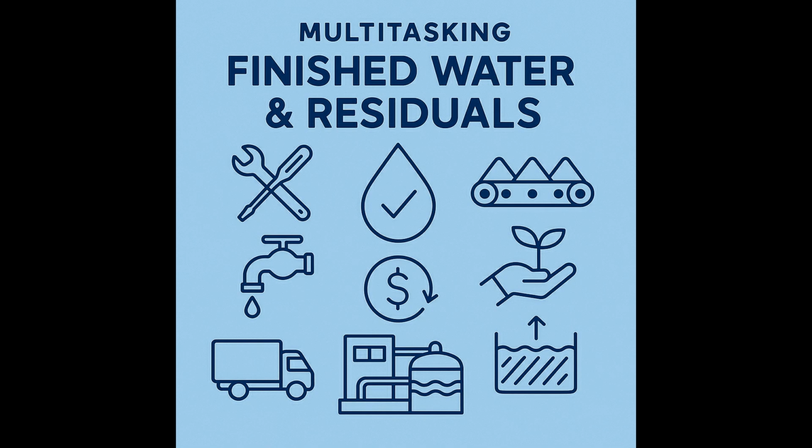Makes sense. You also mentioned operating hours. How does that play into ROI? Well, operating hours and shift schedules tie into staffing and storage. Some plants might choose to process residuals only during, say, the day shift. This might require investing in larger storage capacity to hold the sludge generated overnight and on weekends. The potential ROI there is lower labor costs. Versus running 24/7. Right. Running 24/7 might require less storage investment, but could mean higher continuous labor and energy cost.